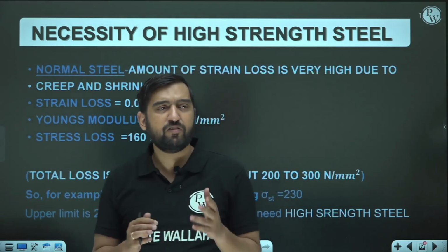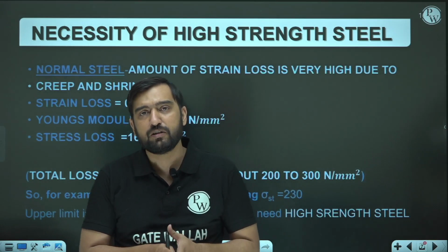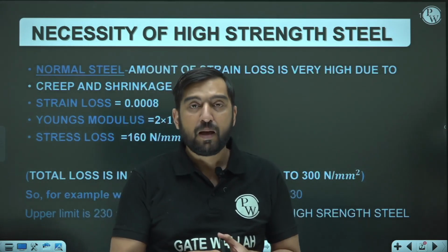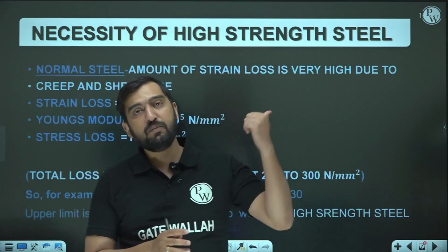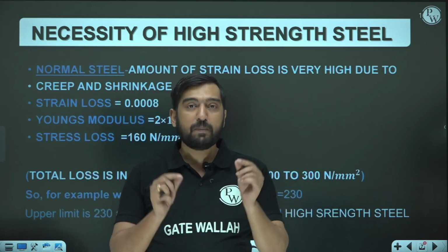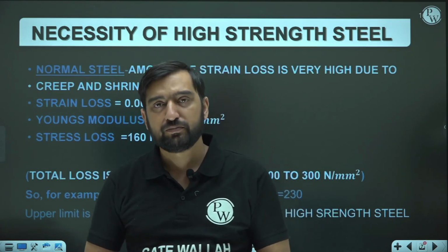And if it is a severe construction, like construction near the seashore or underwater, then we need to go at least with M30. But my dear friend, in extreme conditions there you were using M30, M35 or M40, but pre-stressed concrete starts itself with M30.